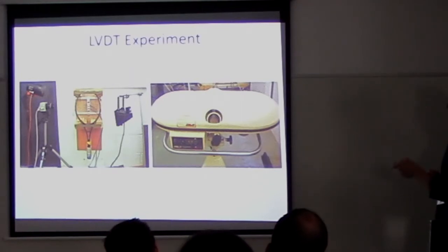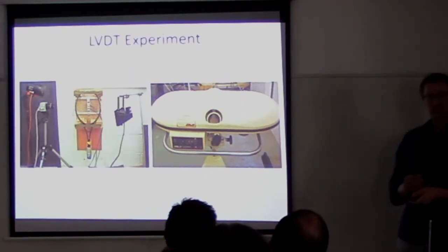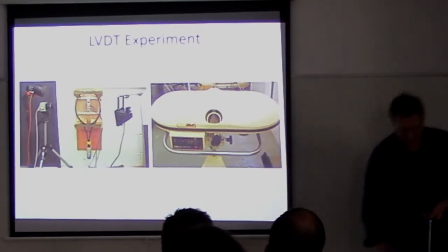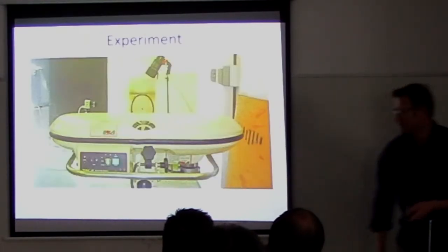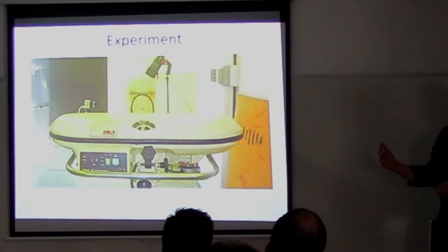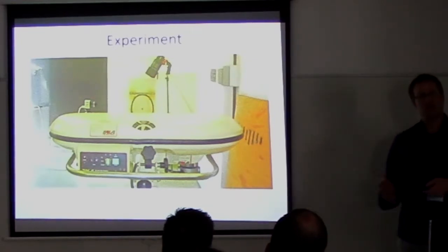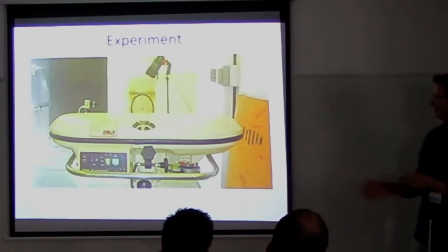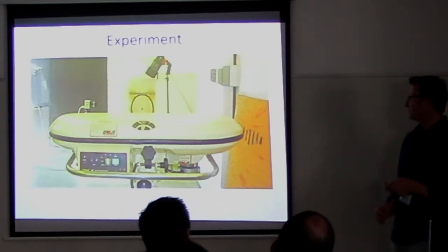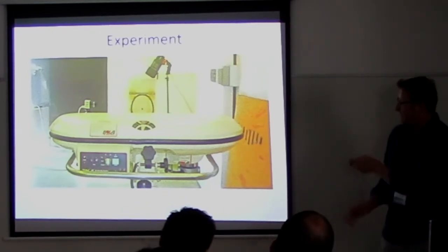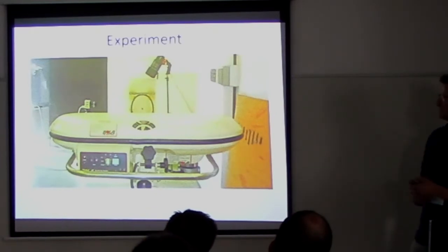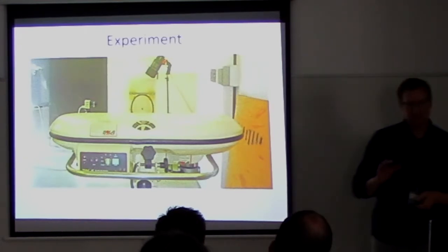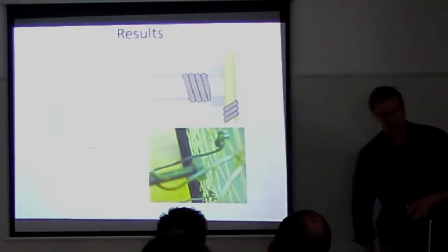of the tennis racket. We then took a bowler machine, which is actually used for launching cricket balls, chopped the legs down so we had a sensible height, and then fired tennis balls at the string bed. We had to have a little bit of distance, and the reason is quite simple: once the ball comes off the racket, if the machine is too close, it starts ricocheting all around, and we don't want it to affect our results. This is the basic setup, and the trick is that, although this machine is quite consistent, the problem is how do you constantly hit the centre point? But at a certain speed, around 30 miles an hour, we were able to do that.